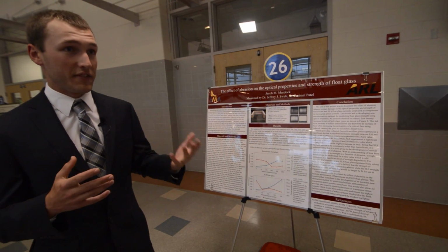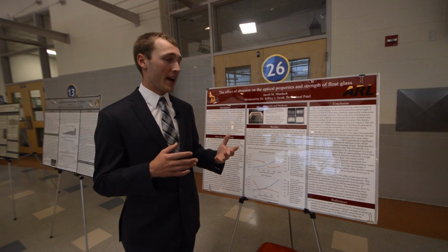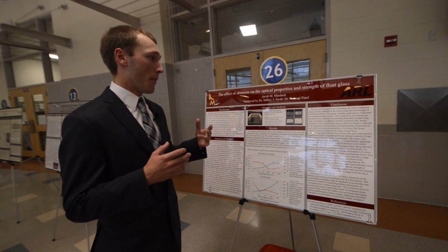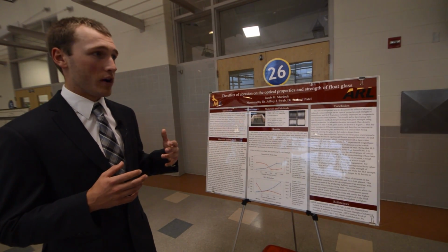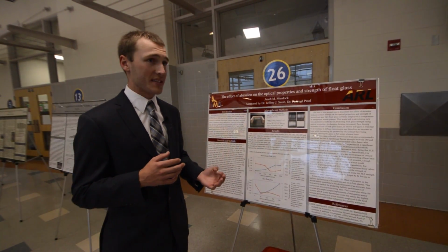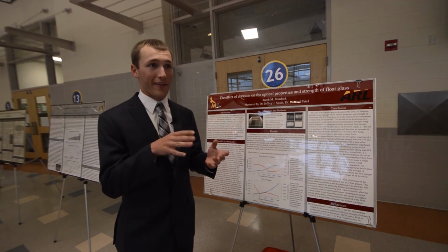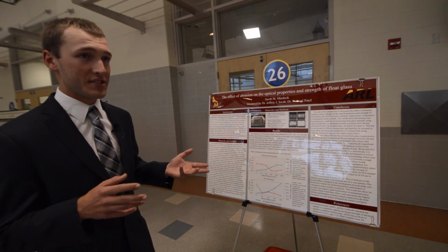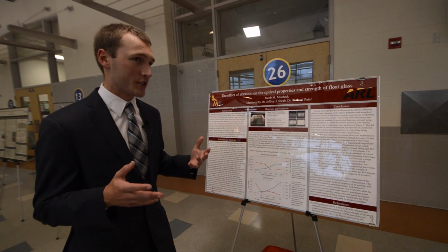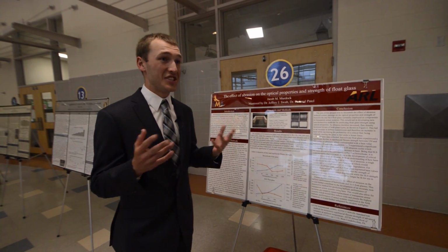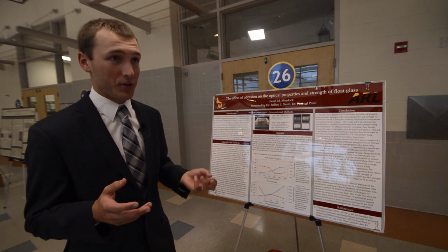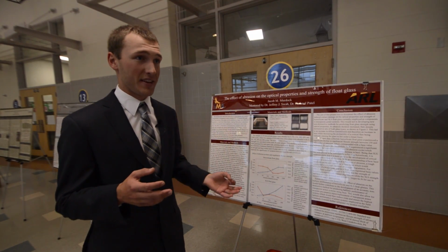In the long run, the conventional method for determining strength is ballistics testing. Ballistics testing involves destroying the plate in the process, due to the fact that we're firing a projectile at it. And the problem is, your results may reveal that the float glass was perfectly fine to begin with and didn't need to be destroyed. Ballistics testing is a destructive methodology.